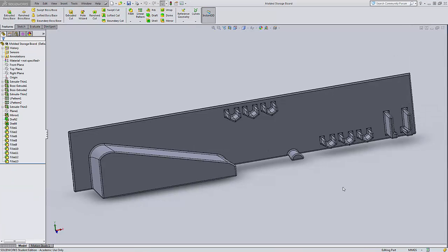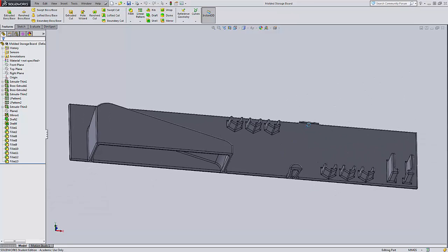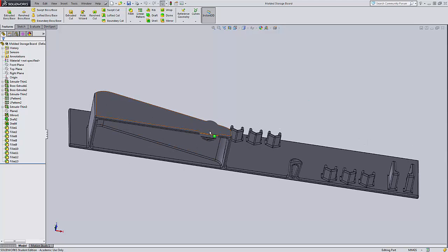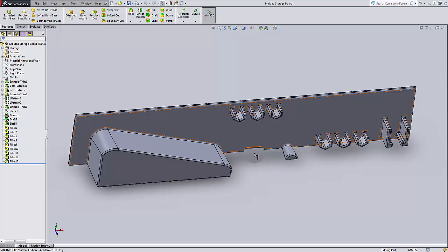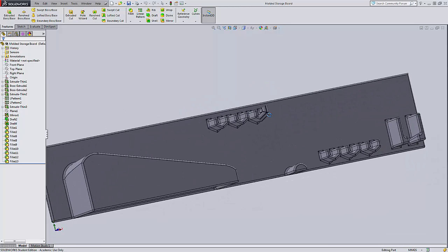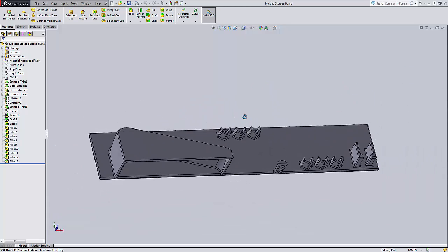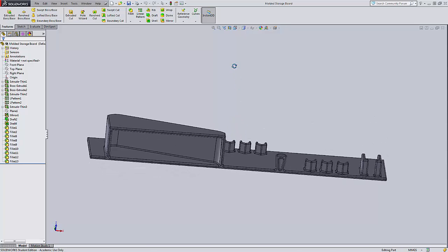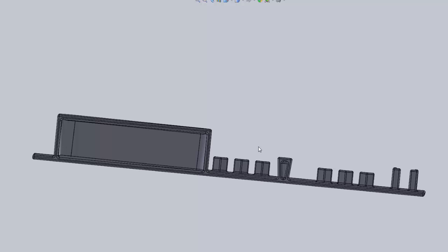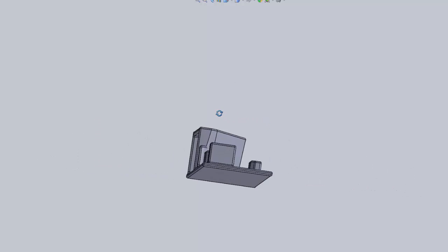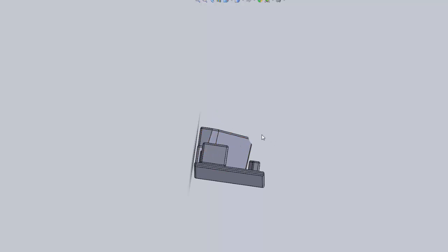So in summary, this is specifically an injection molded part. According to that design intent, we keep nice thin walls everywhere, including up here. And to work towards a cheap one, we wanted the injection mold just to be able to come out towards us here and away from us there, or in this case, to the left and to the right.